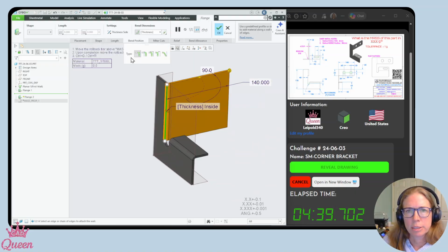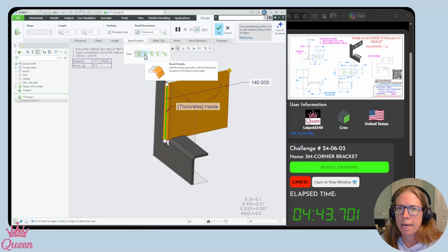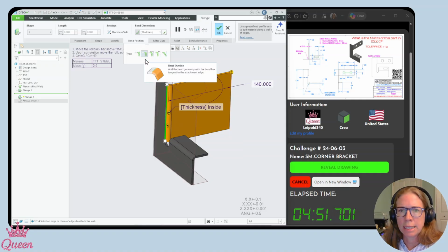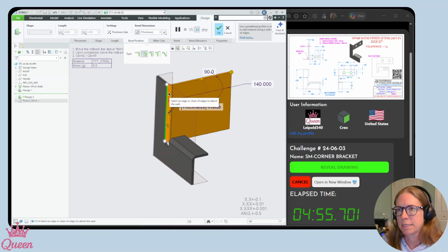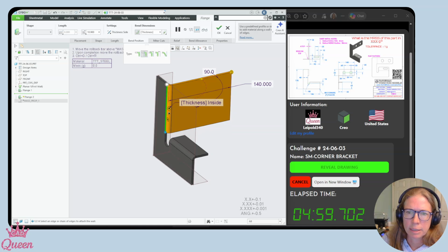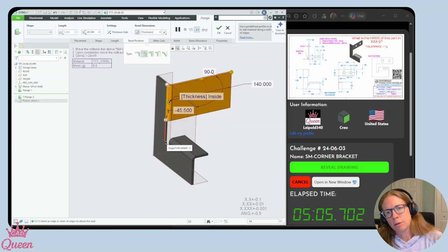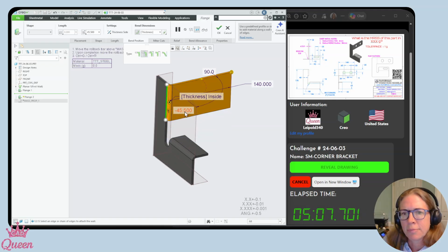And let's go to bend position. Here, I actually want to keep my original edge and then add the wall past it. So I'm going with this 40. I want to keep the original line and then add all the round and the geometry past that original line. I know I want this number to come up, and I see that it's giving me a distance here of how much I'm coming in away from the end of the chain.